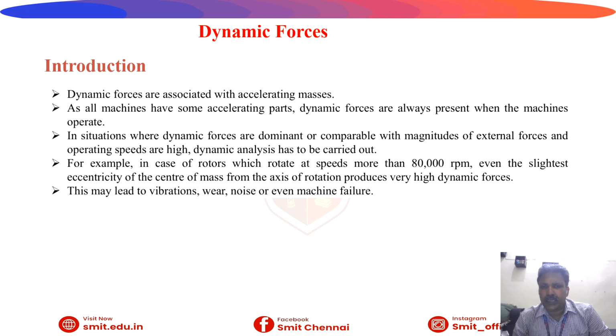For example, rotors rotate at speeds of more than 80,000 rpm. Even the slightest eccentricity of the center of mass from the axis of rotation produces very high dynamic forces. This may lead to vibration, wear, noise, or even machine failure.